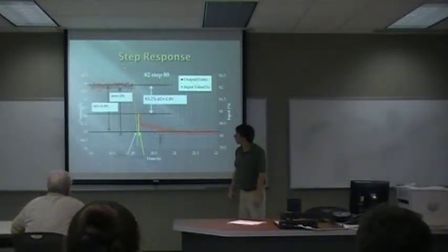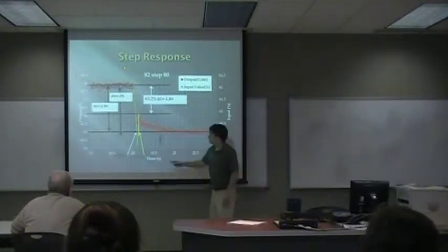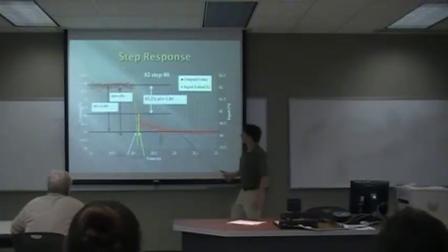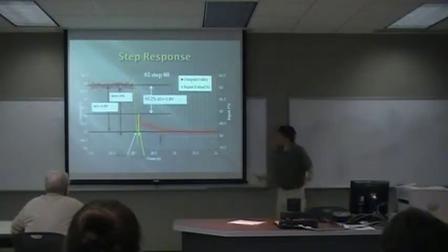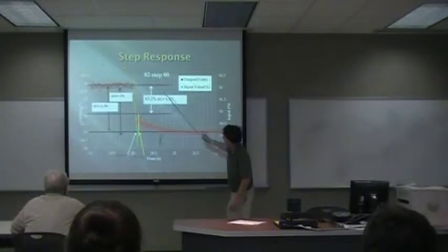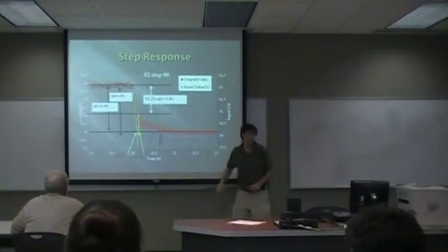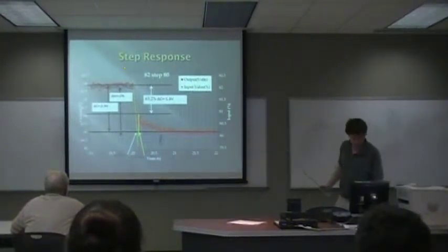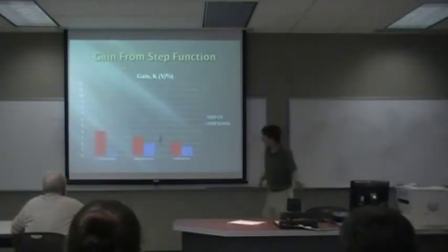So this is the step down from 82% input to 80% right here. As you can see, it's focused in on where the actual step down occurs, dropping from 82% input to 80%. And it curves down gradually. It allows you to find patterns about parameters. There you go. So from those results, we got the gain of the system.